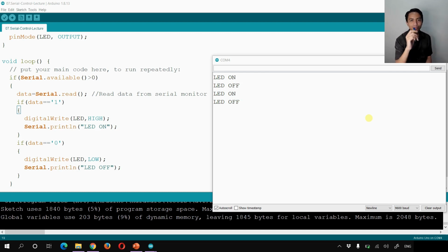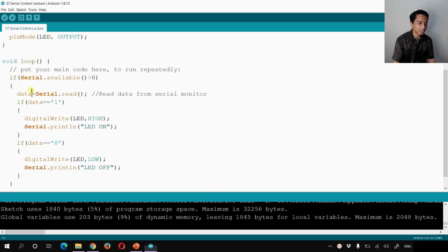If you want to try to control your Arduino using Bluetooth, you can choose this HC05 here, connect it to your Arduino, and try to communicate with it. Then pair it with your phone's Bluetooth, and using any app that you can find available in the Play Store, you can send characters, whatever characters, to the Arduino. Use this Arduino IDE, with a little bit of editing that you need to do, to translate that information, that character, into action. What action you want to do, or what action you want to ask your Arduino to do.